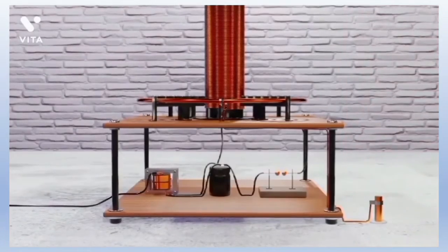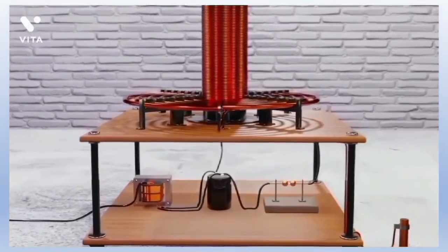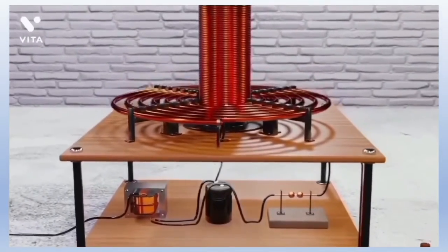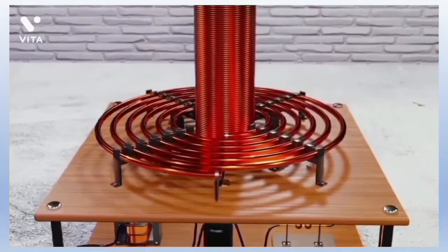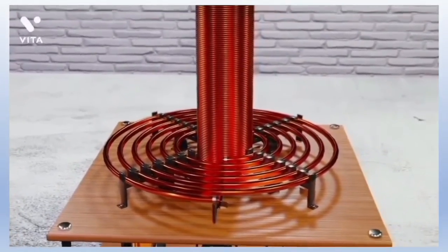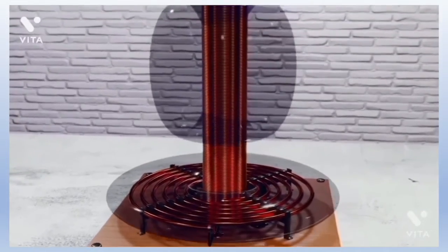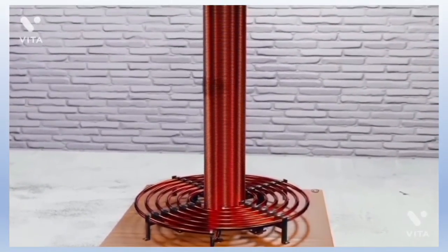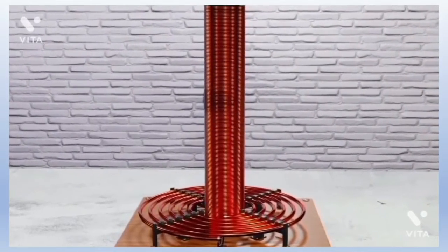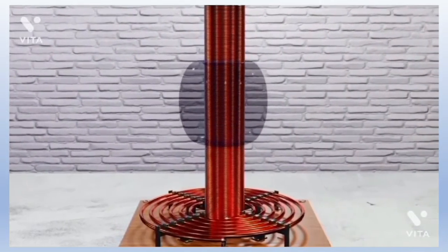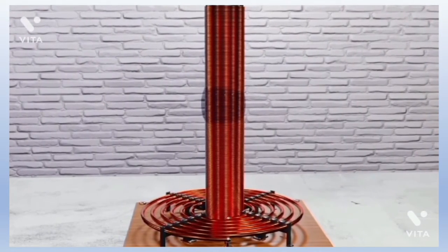The last detail of the operation of a Tesla coil is in the form of the primary coil, which is designed with the aim of reducing the magnetic coupling between both coils. In practical terms, this means that when a voltage oscillation goes through the primary coil, the secondary coil will generate a higher voltage due to the difference in the number of turns between both coils. But it will also continue to oscillate, even if the primary coil stopped working.